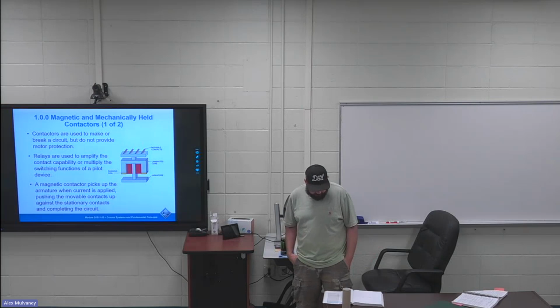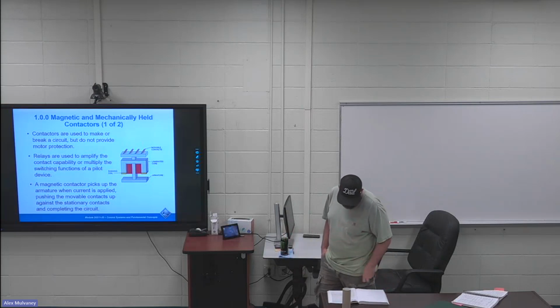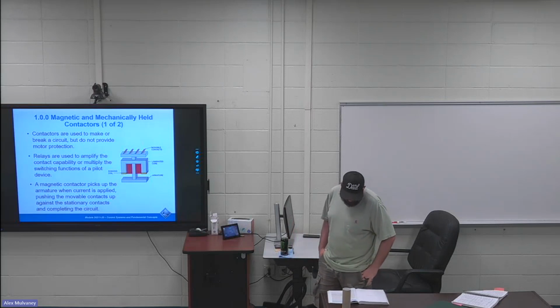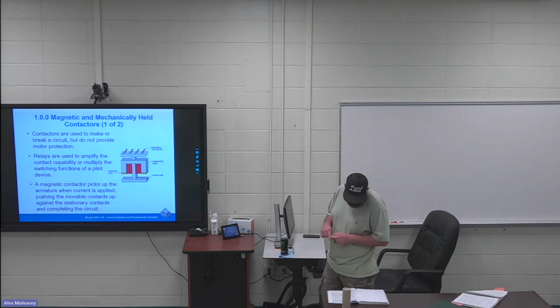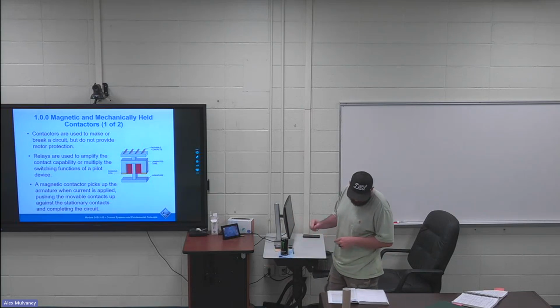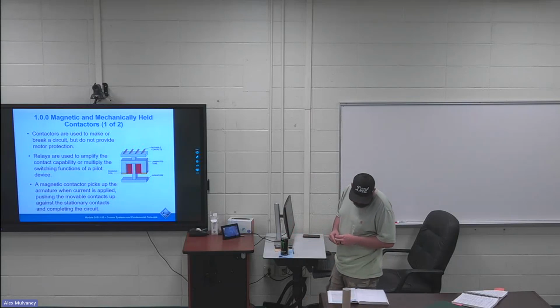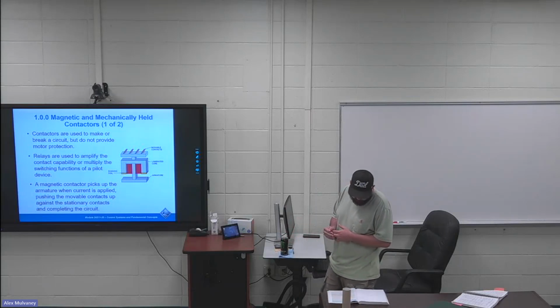So my first highlight is the first paragraph. It's going to be the first few sentences. A contactor is an electromagnetic apparatus that's designed to handle relatively high currents. The conventional contactor is identical in appearance, construction, and current carrying ability to the equivalent National Electrical Manufacturers Association, NEMA, size magnetic motor starter. The magnetic assembly and coil contacts holding the interlock and other structural features are the same.